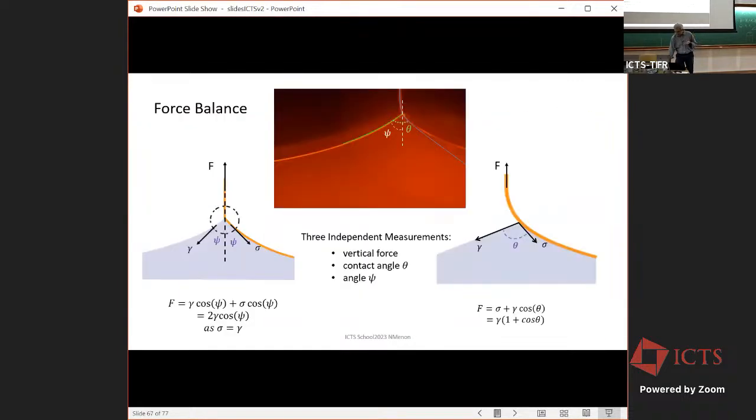You can measure out at this scale, you can measure the force, and you can infer what's happening at a much smaller scale. This is a little bit like Wilhelmy plate measurements in spirit. You can get much higher precision with this because the Wilhelmy plate actually has a big buoyancy correction. This thing weighs nothing.